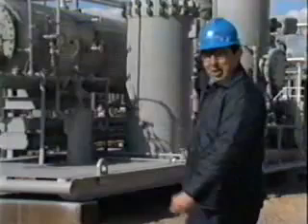For solids removal, fine screens, sock type, or cartridge filters are used. Now, solid particles cause erosion of pump pistons, valve seals, and discs, plugging of equipment, and foaming. Sock filters are the most commonly used type of solids removal. Sock filters contain cylindrical elements that are replaced as they become coated with solids.